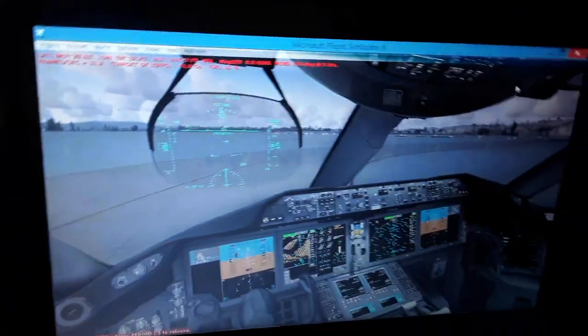We also have the navigation display that shows the GPS position of the aircraft, the terrain, and weather reflections from the weather radar. You can see the red, green, yellow, and amber colors, and also the lakes and rivers in blue. So we can see the terrain depending on its distance from the aircraft, and also the altitude difference between the aircraft and the terrain. We're going to see different colors. Also, in the terrain map we can see where the airports are located, the airport maps, the runways, and the taxiways we can use.